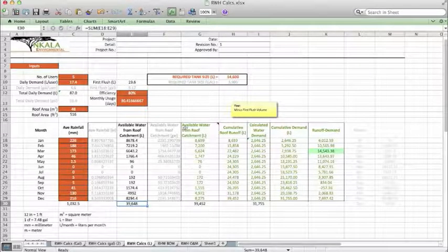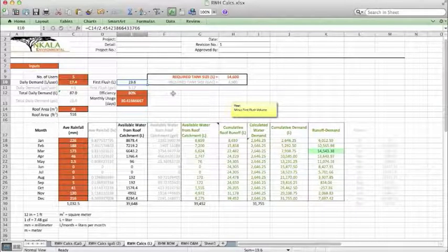Next, what we've done is we said, well, that's not exactly the rain that will be going into our tank. That's not necessarily what's going to be available, because we're going to remove a portion of that rainfall from our system every time it rains. And what is that portion? That's our first flush, right? Because we're removing, in this case, just under 20 liters of the available rainfall. That means that water is not going to be a part of our system. It's going to go into overflow and down a channel, but it's not going to be captured. So we're essentially treating it as if it's not used in the system, and we're subtracting that value off, and that's what we see in this column.